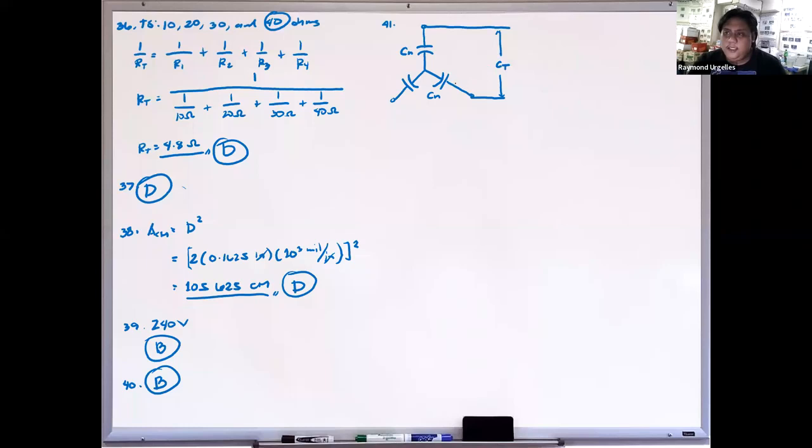This is just given by the series combination of our two capacitances. So this capacitance is given by Cn divided by 2. So the capacitance to neutral is 2 multiplied by the terminal capacitance. That's 2 microfarad from the given, so this will be 4 microfarad. Then what's the charging current?